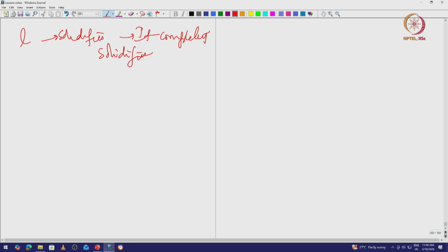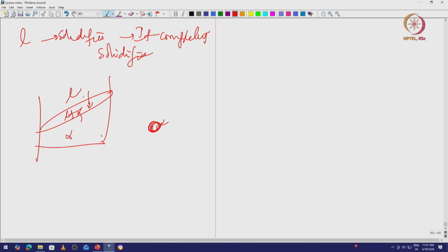It is not like if I have any other phase diagram. So, this is liquid plus alpha, this is alpha. This is an isomorphous phase diagram. If I use this for soldering, I start cooling the liquid down. First the liquid is there, of some metal, and then part of it is solidified, and part of it starts flowing. So, there is a mess. It makes a mess. I want to just put my liquid there and completely cool it.